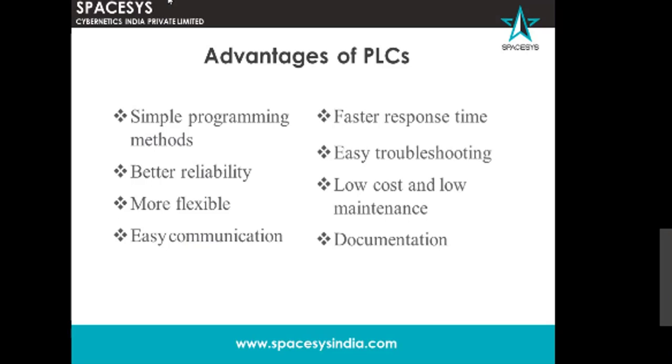Also, PLC can be interfaced with other devices and servers using communication networks, like it can be connected to SCADA, DCS systems, etc. So it allows easy communication. Faster response time. It has a faster response time since it has a very short scan time. Reading the inputs, processing and executing operations are done at very high speed.